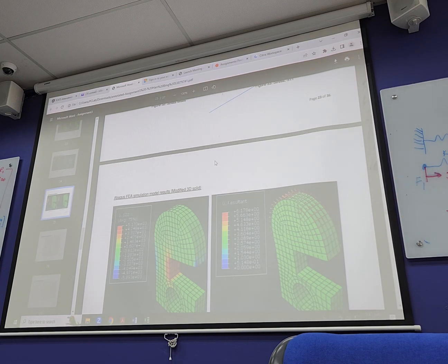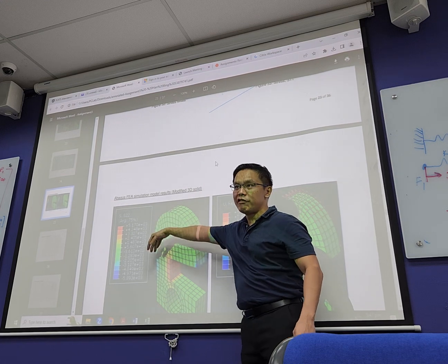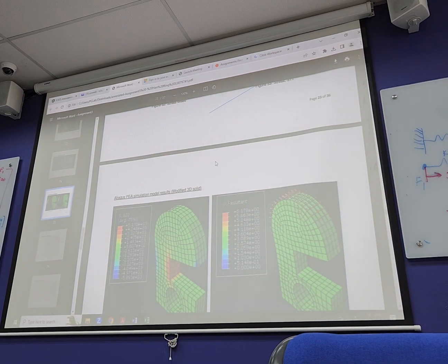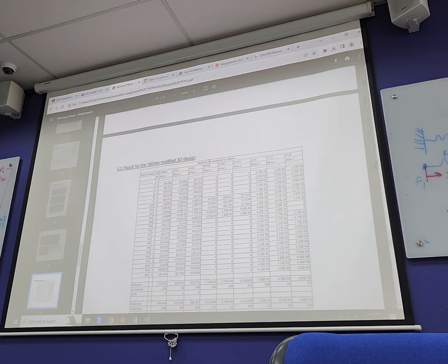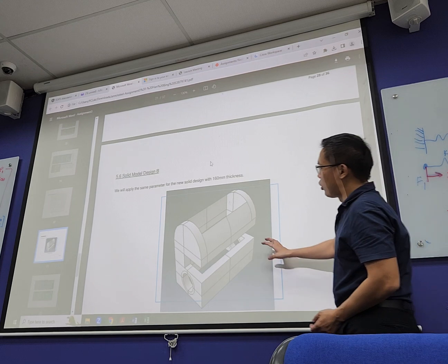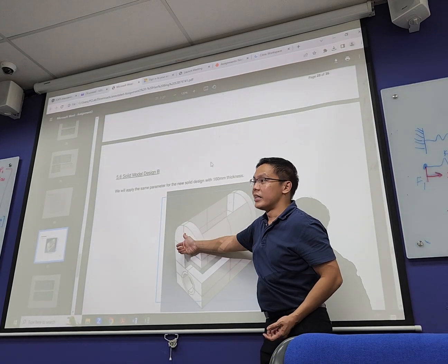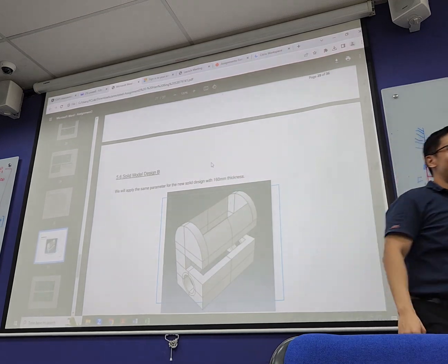That's why I said it is important for you to learn your software on your own. After that, refine the design. How do I refine the design? I do a curved cantilever beam so that I can increase material only when the cantilever moment increases, which you're going to see in the con rod even more. Then cut through, because I'm only interested in the bending stress in the thickness direction, so I can remove some of the material here.